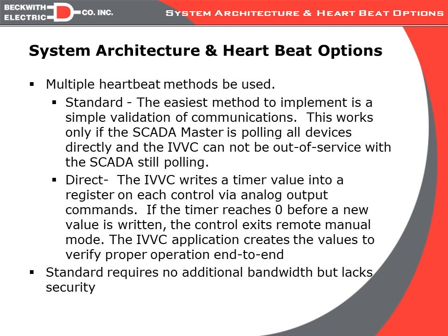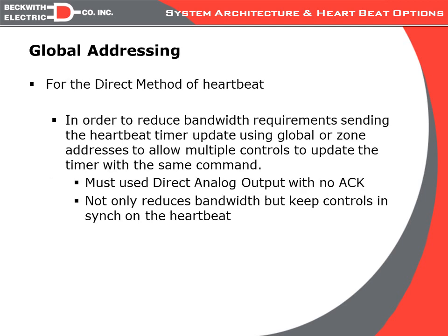The direct mode is a little bit more complex, in that we still have a timer value setting in the control, but what reinitializes that value is not any valid communications, but a specific write from the IVVC software into that register to bring it back to a new positive value. If we reach 0 before we get that, then we're going to come out on our own. The disadvantage, obviously, is it's going to require additional bandwidth to do that.